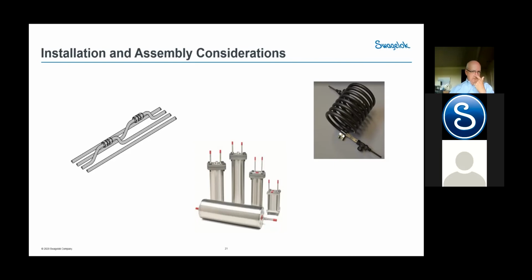So the next thing is flanges. People say their flanges leak. Flanges do not leak, but with flanges today, you have to know the torque spec and the torque pattern. And flanges only take up axial movement. They don't take up any other movement but axial. When we're looking at flanges, there's movement besides axial, and the flange will leak.